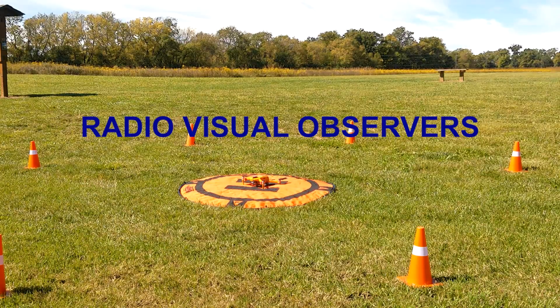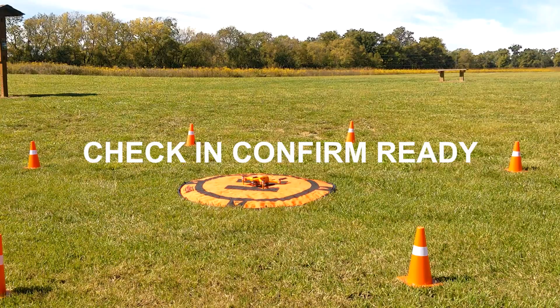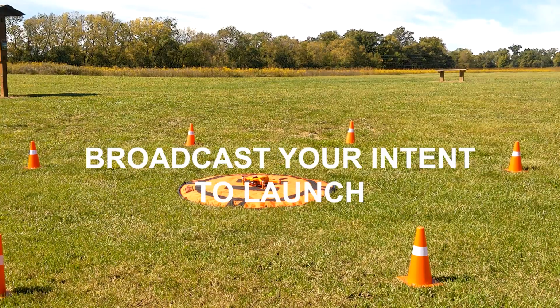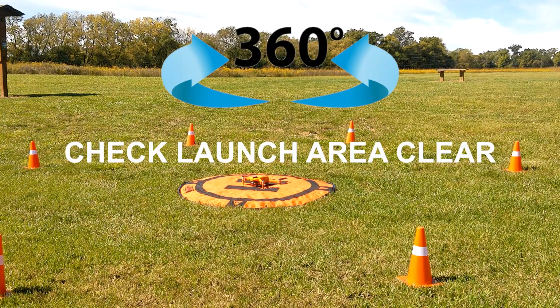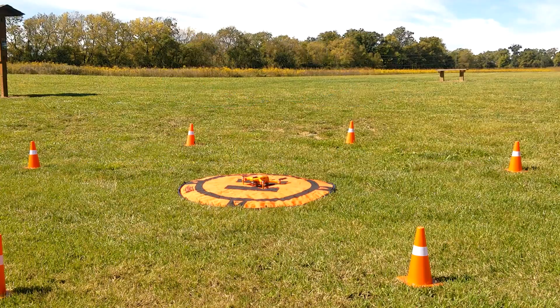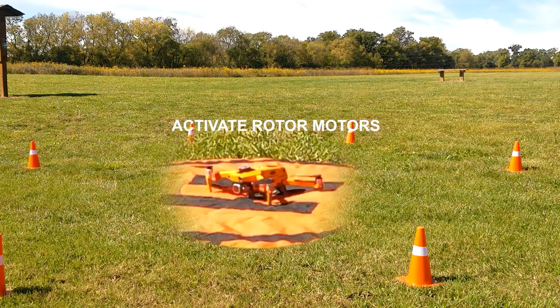If you're going to be using visual observers, radio them to check in and confirm that they're ready. Then broadcast your intent to launch. Now we need to check and make sure that our launch area is clear. At this point, you're free to activate your rotor motors.